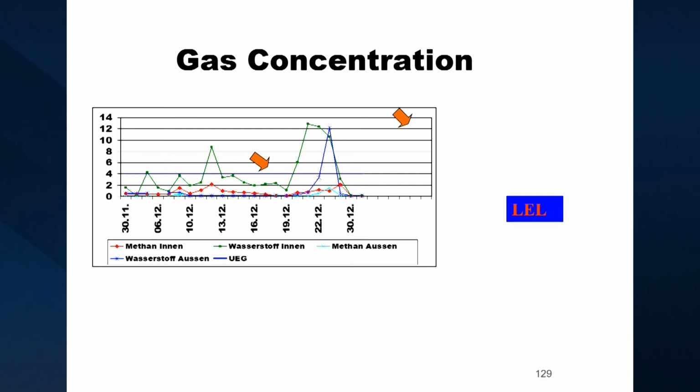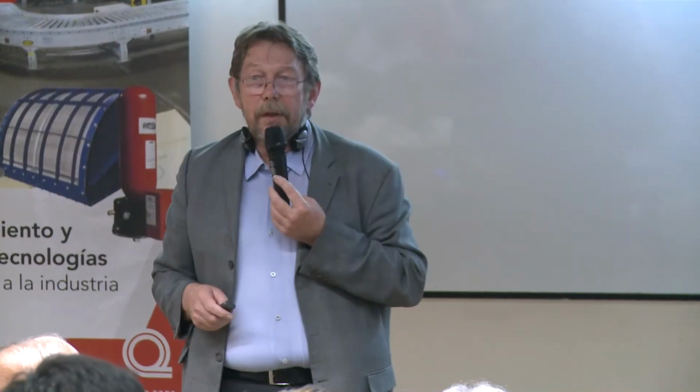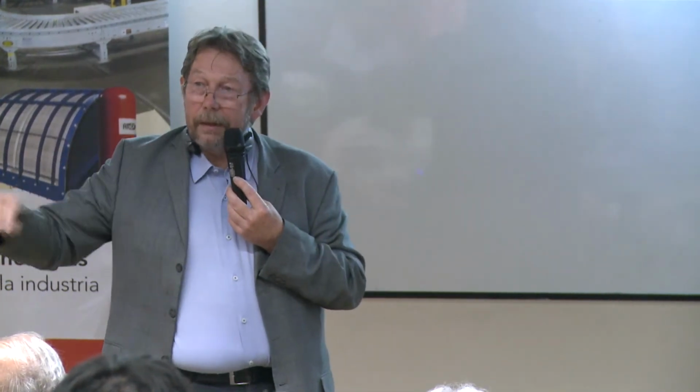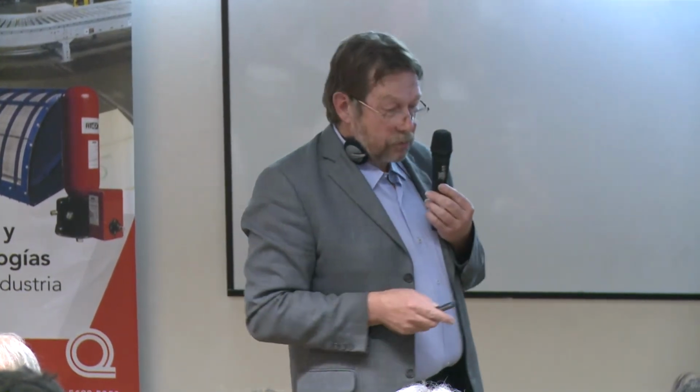What we then finally used was some kind of starch with water. It's the glue that you use for putting wallpaper onto a wall. And we covered the top of the silo with about a 1 meter layer of this starch to make sure that we got the draft out of this process, and that we didn't create gas concentrations in the empty volume, to make sure that we couldn't get a gas explosion.